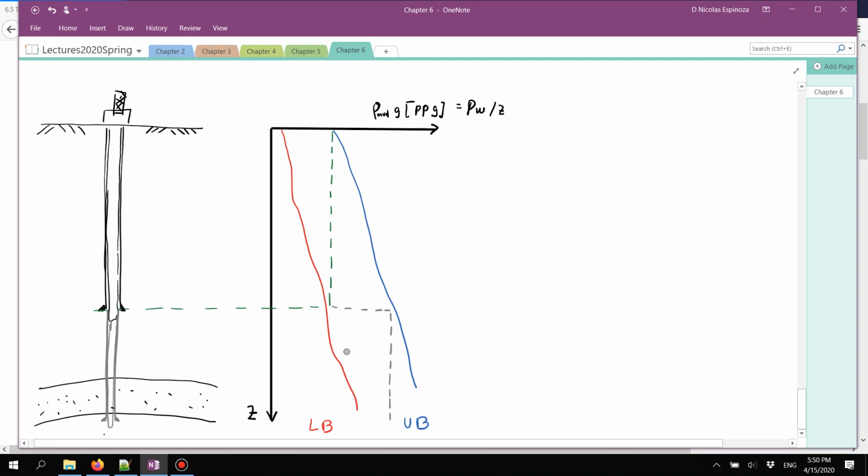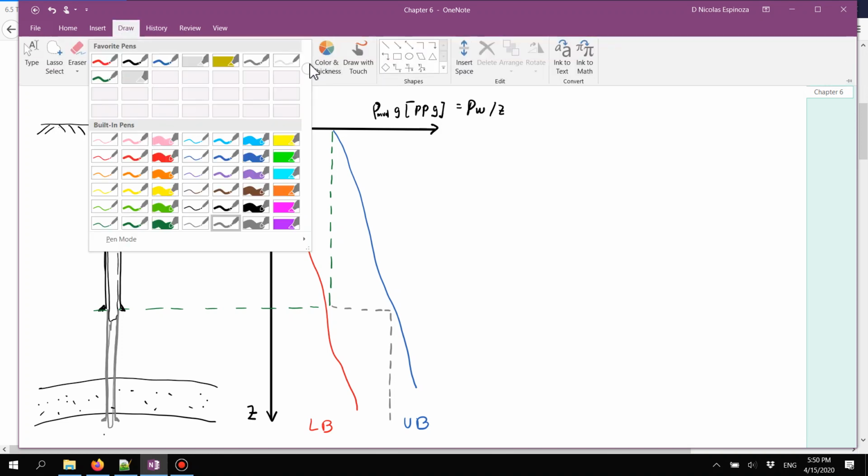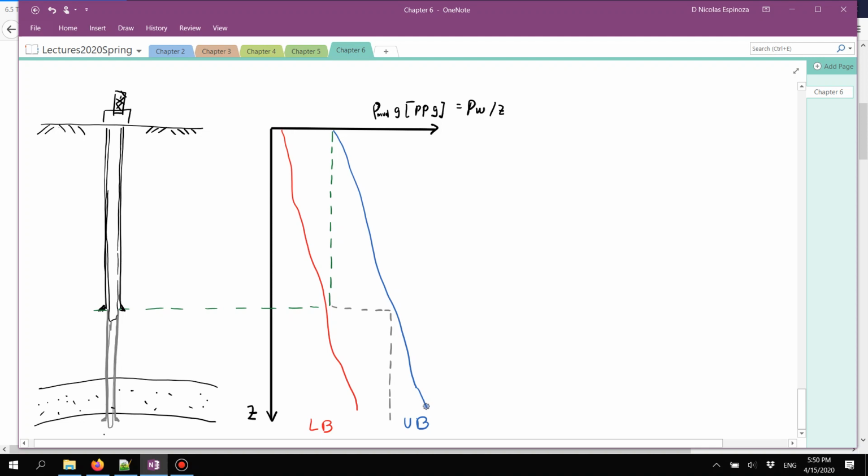It's also super important to determine the lower bound and the upper bound accurately and to be as large as possible, because if I was doing a poor job and, for example, I determined the upper bound somewhere over here, now I hope you can see that we will have to use a lot more casing stages in order to do the same job. So we'll have to do this and then case, go again, case, and go again. So probably in this case, with this upper bound, I would need 3 casings, which will be less desirable. It will be much better just to do it with 2.